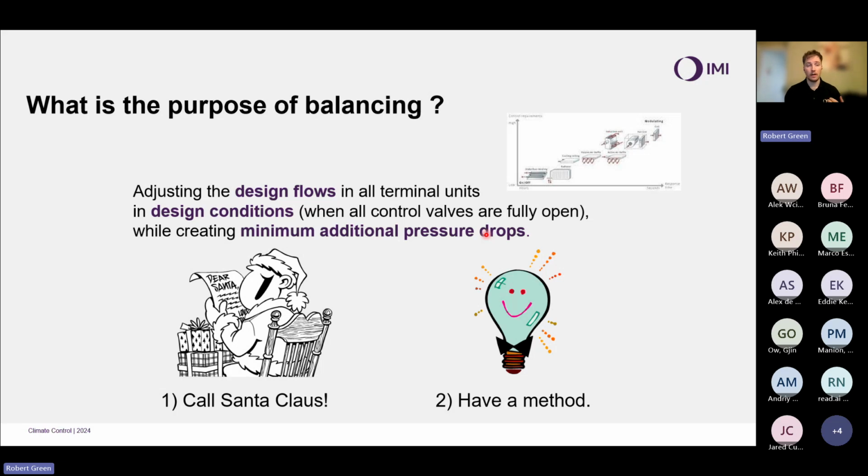On the back of that, we also covered how to optimize with dynamic balancing devices, and a couple of our key balancing methodologies with our TA scope. HySelect in particular, which we'll cover today, really helps with these methods because it builds up a network that I can then upload to my TA scope and run some of these self-balancing techniques, the TA wireless and TA diagnostic technique we looked at. So today we're going to cover how we design systems to be balanced and how HySelect can enable that.